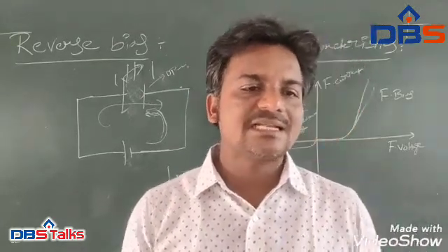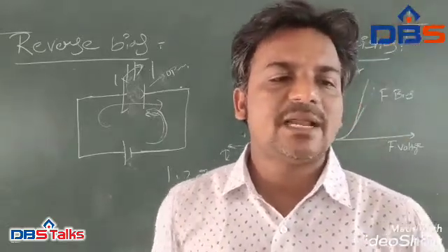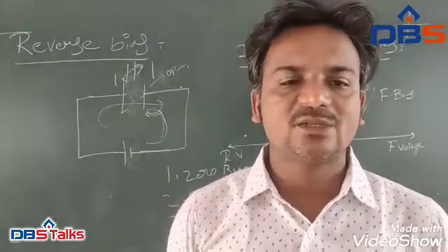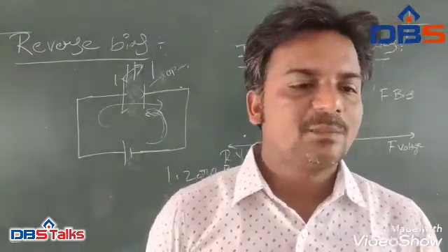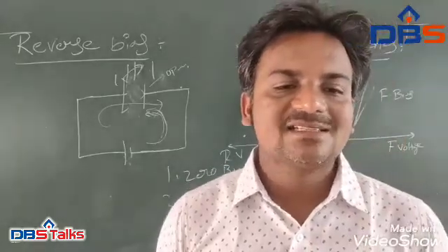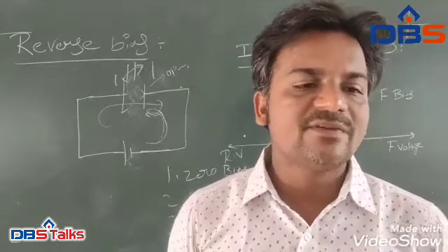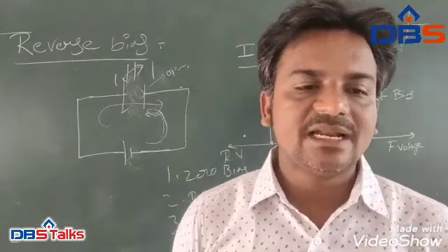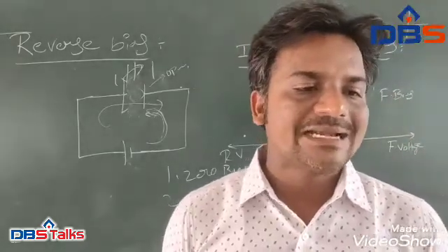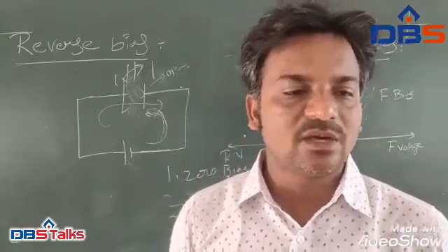When the diode is connected in a reverse bias condition, a positive voltage is applied to the N-type material and the negative voltage is applied to the P-type material. The positive voltage applied to N-type material attracts electrons towards the positive electrode and away from the junction, while the holes in the P-type are also attracted away from the junction towards the negative electrode.